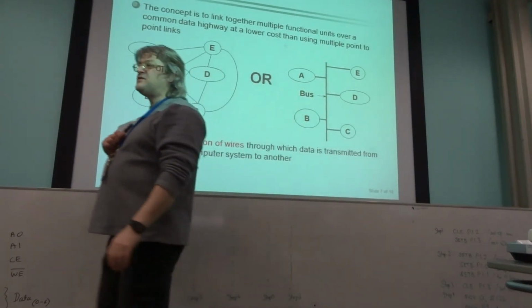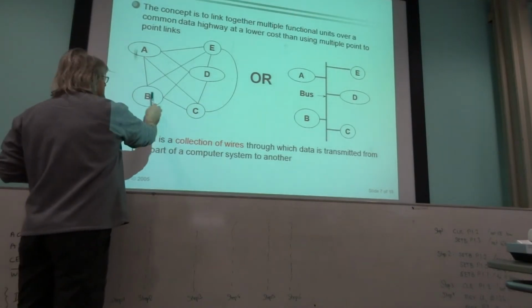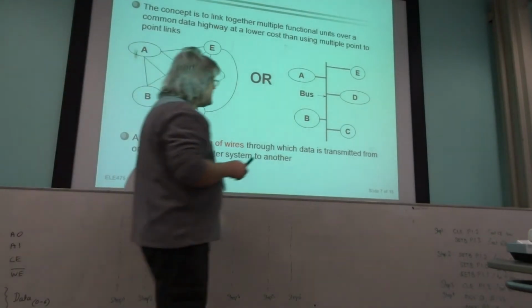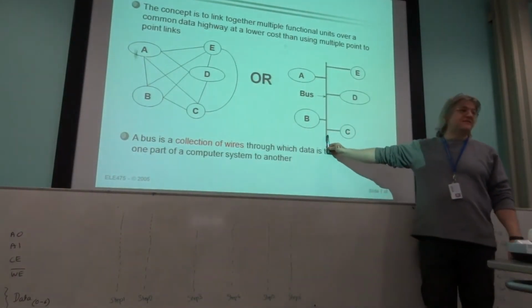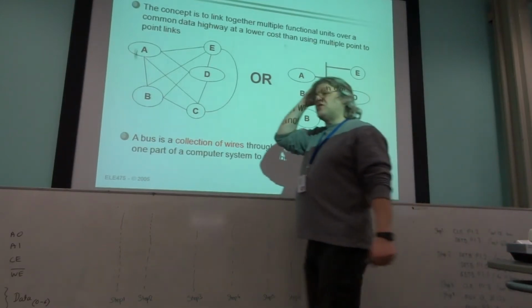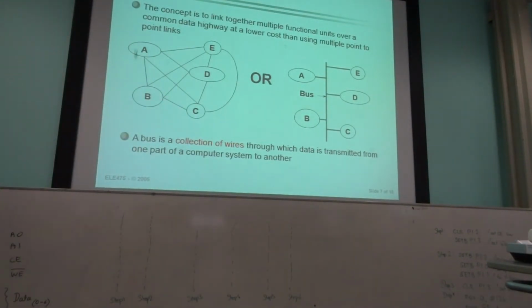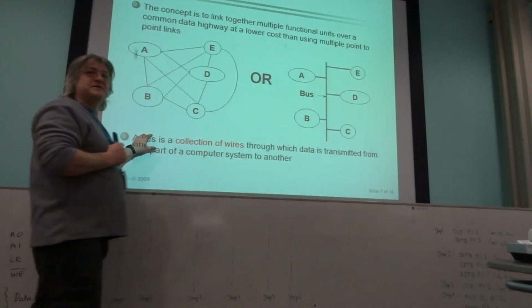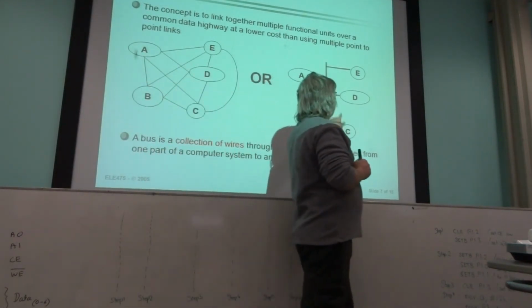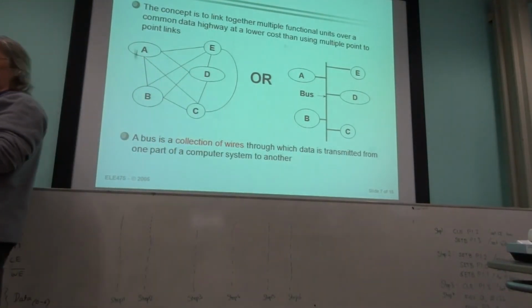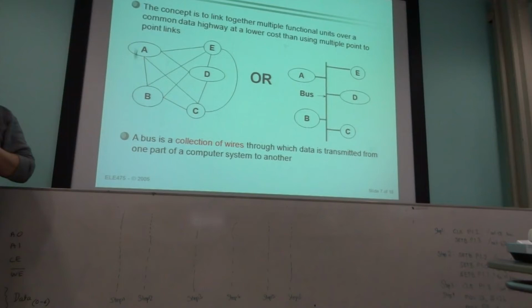The key difference between the two is where each of these particular devices have dedicated signal pathways. In this example over here, there is a shared signal pathway between the various entities. A shared collection of parallel wires we usually refer to as a bus. It doesn't actually say the word shared there, but a practical bus, the whole point of it is we're allowing multiple devices to have access to it. You can't let them write to it at the same time.